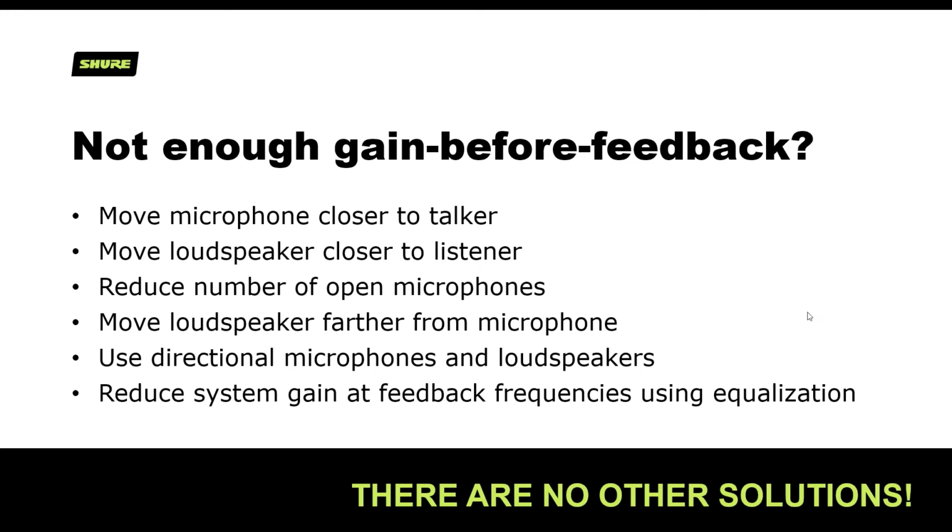Number one, move the microphone closer to the talker. If you can't get that changed, then move the loudspeaker closer to the listener. Because remember, the closer the loudspeaker is to the listener, the less you need to turn it up. The less you need to turn it up, the less likely you are to get feedback. Keep the number of open microphones as small as possible. Use an automatic mixer if it's a speech application to keep that number of open mics as small as possible.